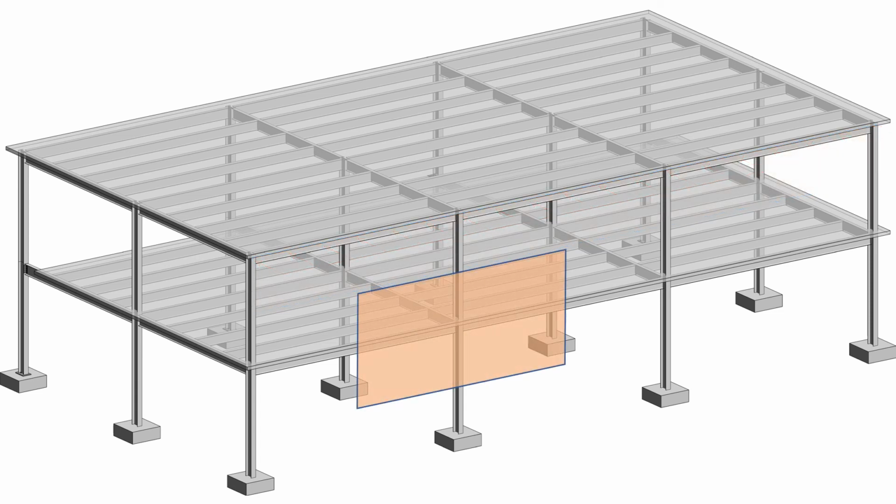Occasionally, when we look at tributary area on facades or wall units, we look at the amount of force that's entering each node in the building. So rather than looking at a strip that covers the full width of the building, we might look at a tributary area that is rectangular shaped, and then use that to calculate a point load that is introduced at the intersection of one of the spandrel beams with the columns.